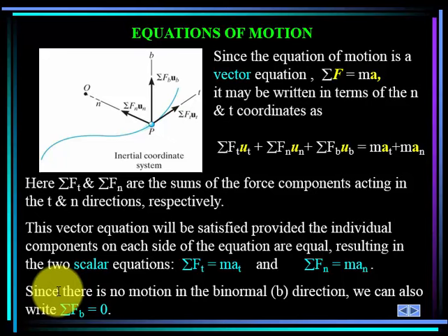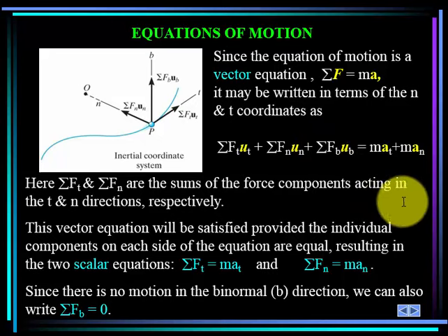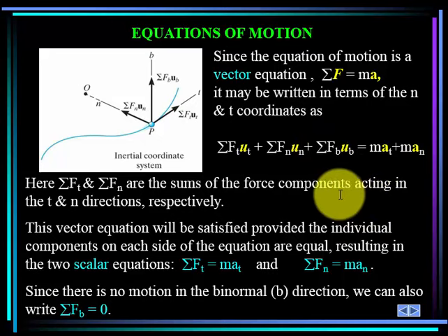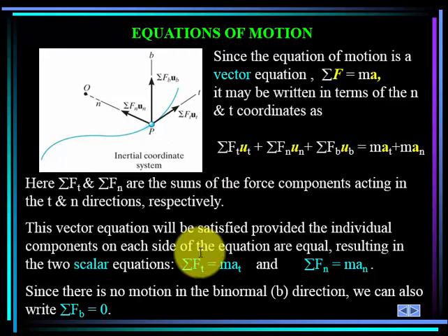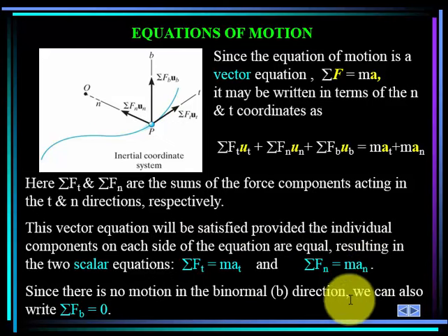that direction would cause us to leave the path, and if the accelerations are zero, then the sum of forces in the binormal direction are also zero. We will then take what's left out of this equation and typically just break it into components: sum of forces in the tangent direction equals mass times acceleration in the tangent, and sum of forces in the normal direction equals mass times acceleration in the normal. We'll say whatever we can that is true by writing these normal-tangent equations of motion.